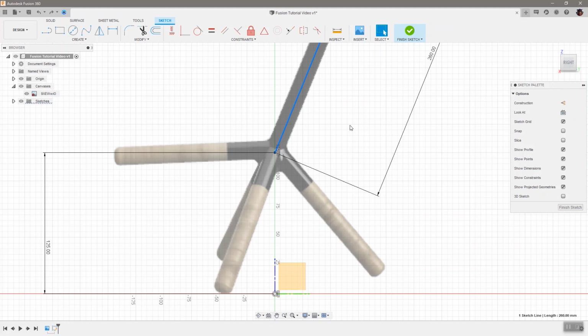I am referencing something outside of the sketch, and my sketch will never be able to rebuild without that axis. Now that is not a problem at all because this axis will always be there. But if you imagine we could reference this line to some other geometry in an assembly, that could be a problem because if that geometry disappears, this sketch could no longer rebuild properly. We'll be talking about those kinds of relationships a little bit more.